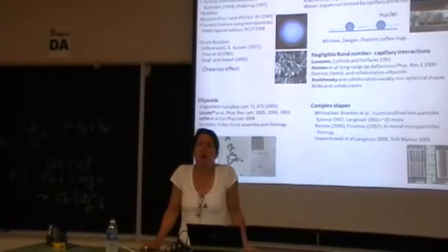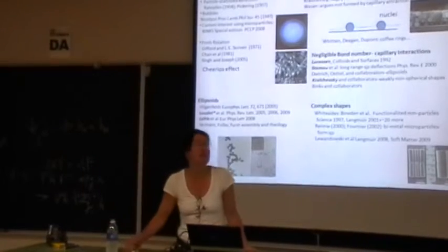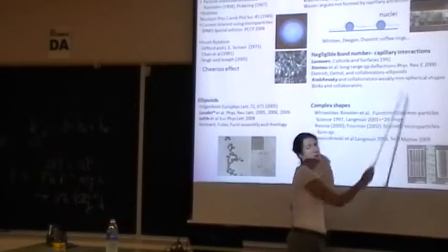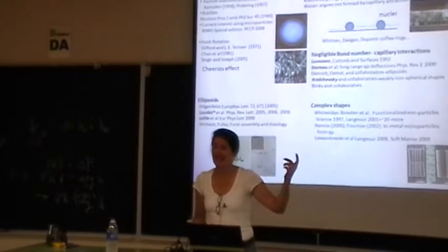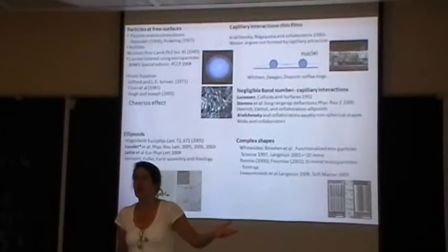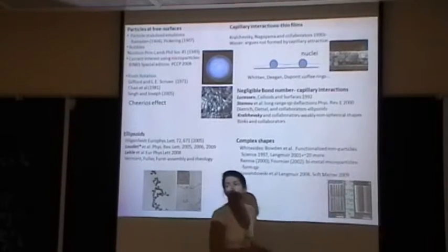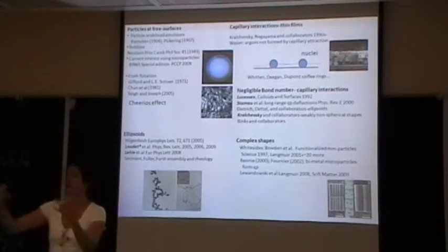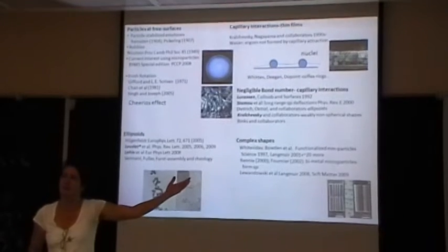Okay. So who cares about a colloidal crystal? Were we trying to commercialize coffee machines? The answer there is no. It works out that in material science, there is value in the ability to make a colloidal crystal. This is a colloidal crystal that was made in my group just so that we could have good pictures to put in talks like these. It's true. We just made it by evaporation. We evaporated a colloidal suspension and the particles were pulled together. As the suspension continues to evaporate, capillary interactions between the particles pull them into crystalline order. And there it is. For free, you've made a crystal.